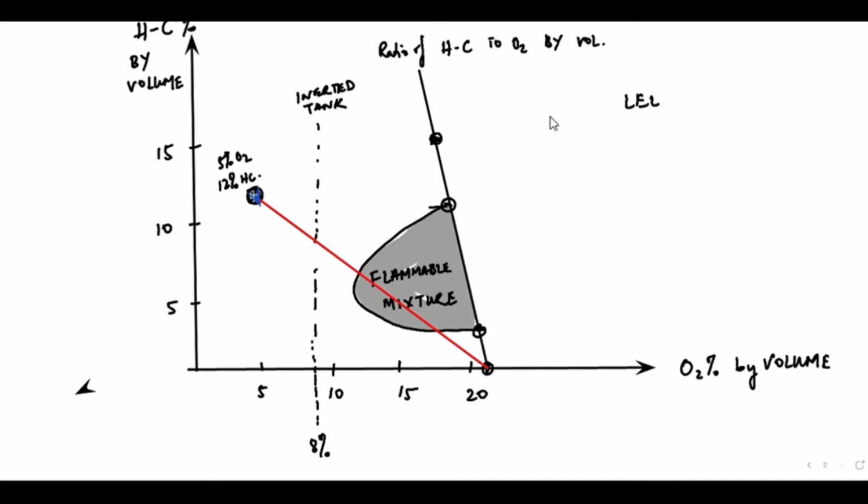By purging, we are going to bring down this hydrocarbon level lower, maybe 5%. Even lower than that, somewhere maybe around here. So this is purging. When we do purging, we have brought it down to somewhere around here. And better still, I bring it down a little bit further, maybe to less than 2%. Yeah, less than 2%, that will be the best. So we bring it down here, where the oxygen may increase a little or if it is reduced also, it's good enough.